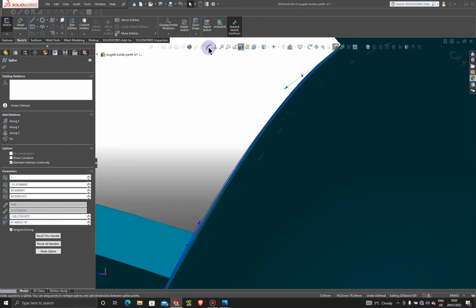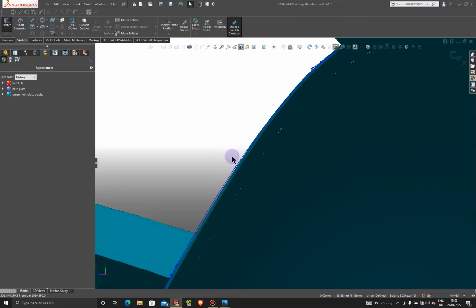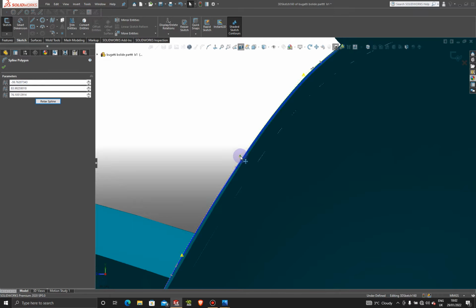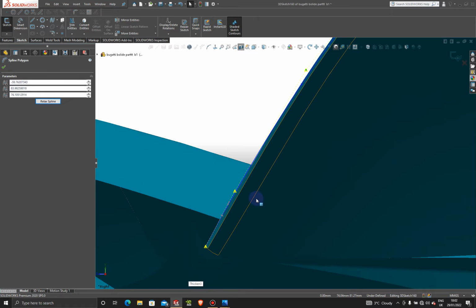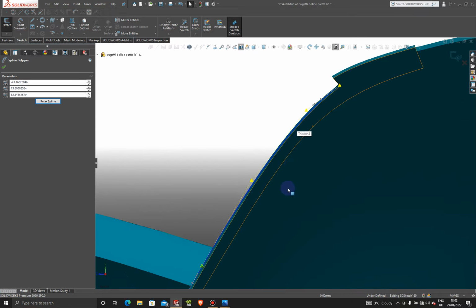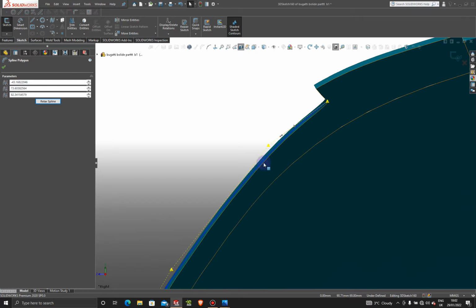Okay, we can maybe try and add a control point in the middle here. Okay, exit the command, and click on the line, and let's add our control polygon. Okay, so this way we can have a lot better control over things. Just a little bit here. It falls all the way into the midsection of this design here. So let's drop this somewhere here and leave that there.